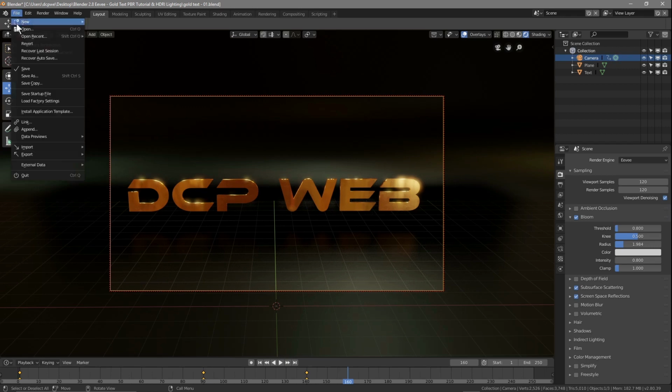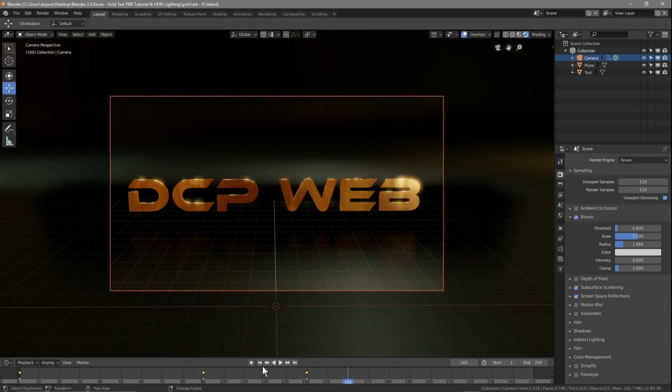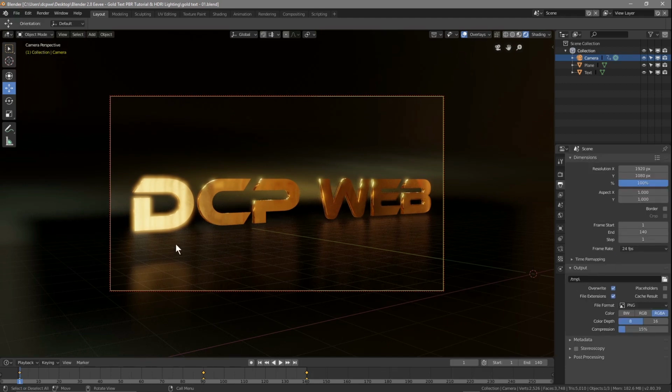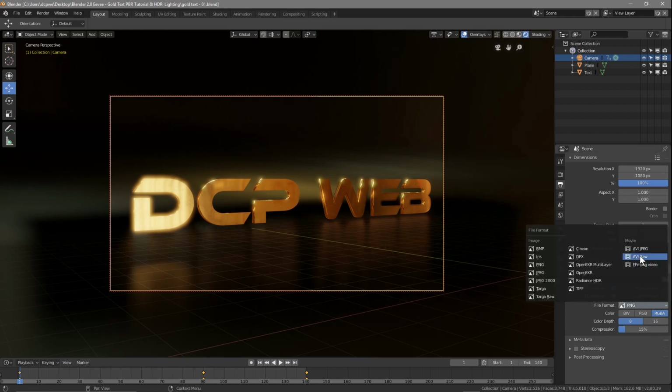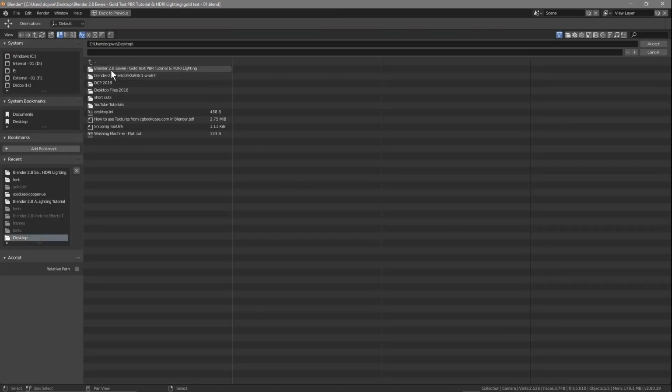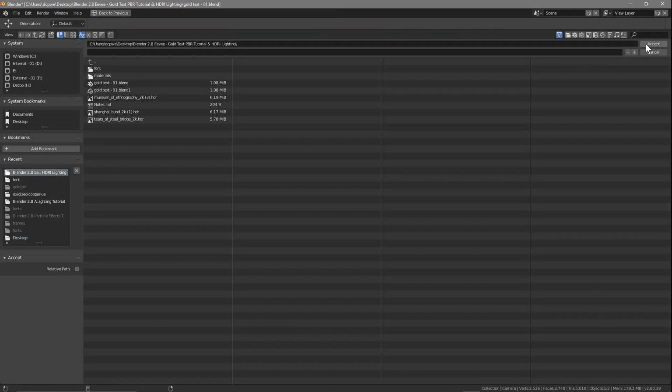That looks okay for now. You can play around with that. We'll save this. Let's go back to the first frame. We've got 140 frames, so we'll set the end frame to 140. Let's just save this and then we'll go to our render settings. Normally I'll render these out as JPEG, PNG files first and then render the video out afterwards, but I'm going to save us a bit of time and just go straight to AVI RAW. Normally I'll do PNG files, so check my beginner's tutorial where we did PNG files first and then created a video sequence afterwards. But I'm just going to go straight to AVI RAW, click RGB, and then we'll navigate to that same folder, and yeah, that'll do.